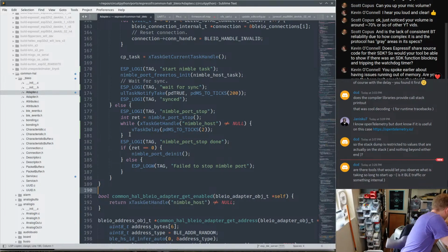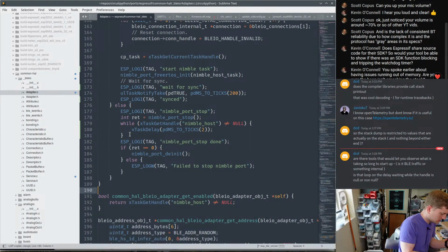So I could take a separate, where did my, yeah, I was using this for convenience. Should I set up benchcam? I'm hooking up, these aren't alligator clips, these are some sort of hook. To TX and RX. I'm going to try to get my debug output coming out of UART, which it might actually already be. And then I don't have to rely on this. I can just leave it connected and I don't have to switch back and forth or anything. It's going to be more reliable.